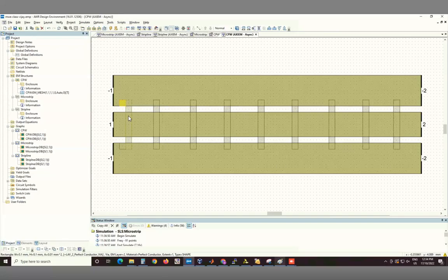You have to go back to that one sentence I kept repeating for the first four lectures over and over again. Defining a potential at one point at microwave frequency has no meaning for the rest of the structure. So at this point, the two ground planes have the same potential. But as you go along, their potentials could change because it can support a wave there, right? Because it's a long distance. So that's why we are continuously reconnecting them so that they don't drift with respect to each other. That was the point of the start of the discussion.